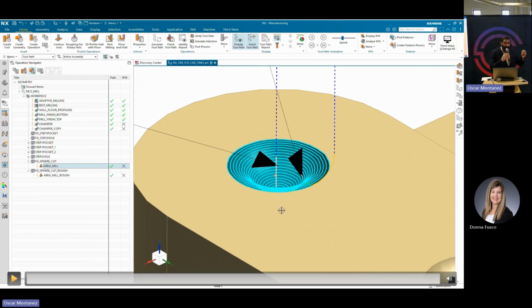In this case, I can directly select the tolerance and get the numeric values in my operation set dialog. But if you want to get the surface roughness, you have to add a step in there. So I'm going to demonstrate that next.